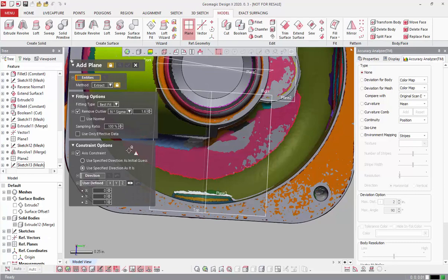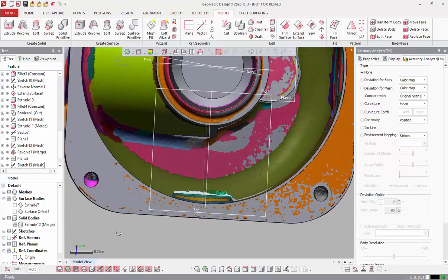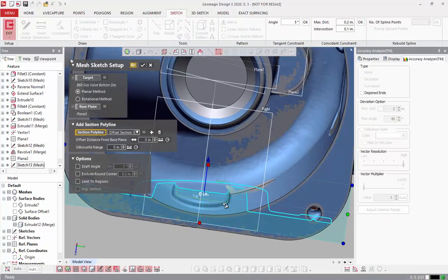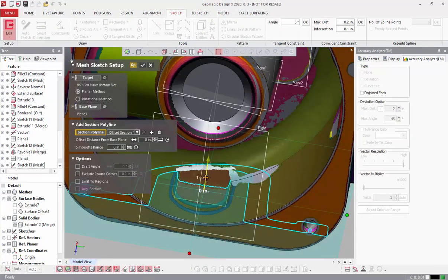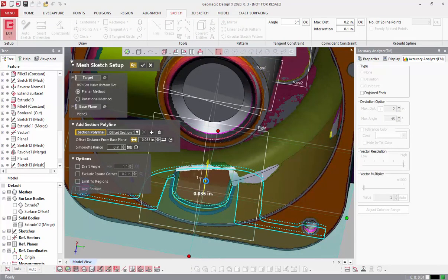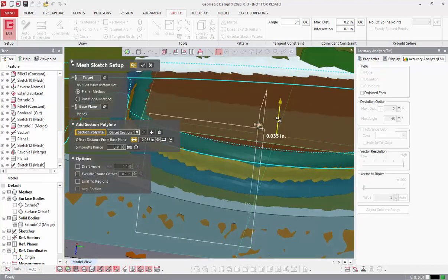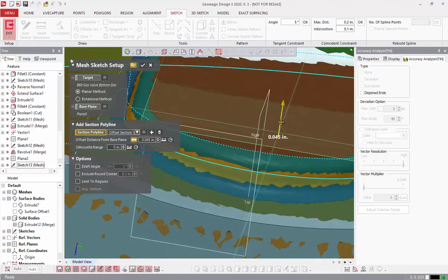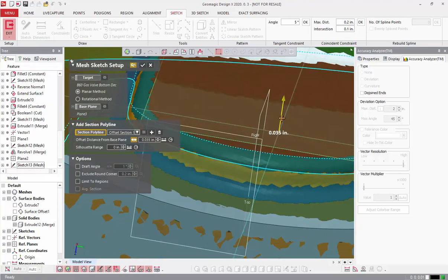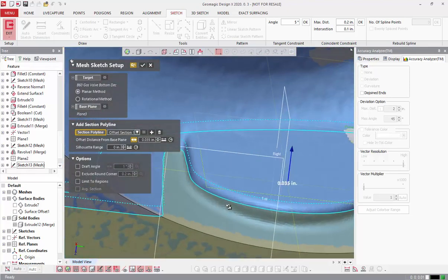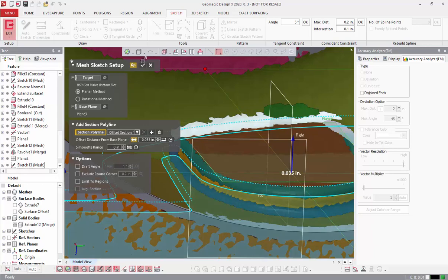And we're just going to model one of these things and then mirror it. Obviously, try and do patterns, save us a little bit of time. So get my cross section set about where I want it. Try and make sure that it's right between those 2 fillets, since this is a fairly thin, skinny part. That looks good.